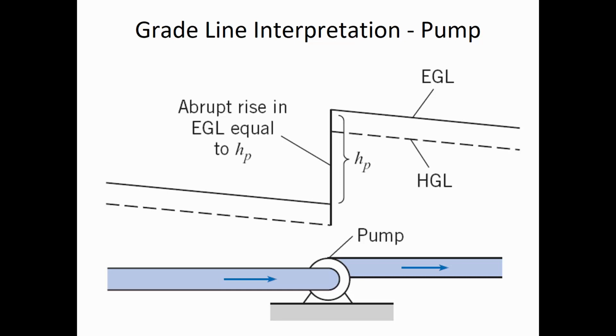That's how, well, some pumps lift the water. You know, a positive displacement pump like a screw pump, or sometimes people will have pumps coming out of a cistern where every time a certain bucket of water tips over, like you see at Disneyland or Disney World, buckets on a rope constantly rotating. That's called a positive displacement pump, and those kinds of pumps are lifting the water physically. But most pumps that are used in homes and businesses and municipal applications are accelerating the flow and adding pressure because of that impeller. And so that's what's happening here.